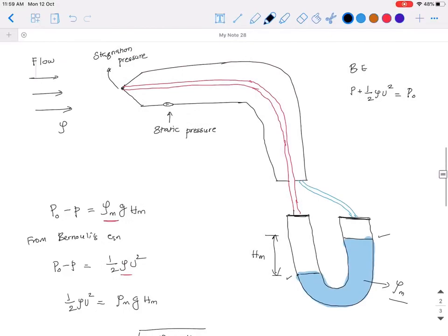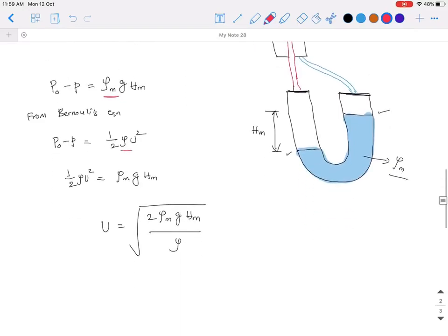So this is how we measure velocity of a fluid flow using a pitot static tube. Here, one point we need to mention is that theoretically stagnation pressure means isentropic deceleration, but in practice isentropic deceleration is not possible. We are bringing the fluid to a sudden halt. This is not an isentropic deceleration, so there will be some error in the computation due to this fact.